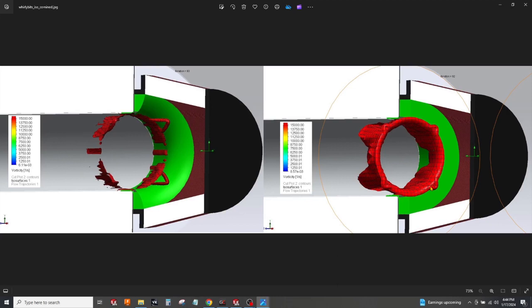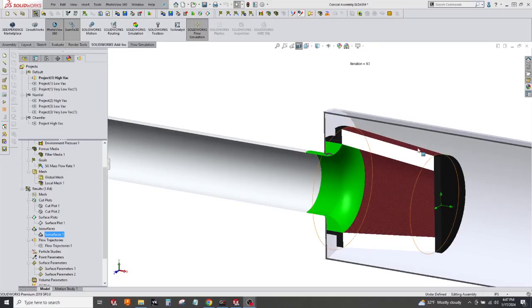So if you are constricted and you can only run a really small intake tube because of how it packages, this is where you're going to see the benefits of this type of thing. So I hope that is helpful. All right, so what have we learned? Well, essentially that velocity stacks are definitely a good thing, especially when you're running really high flow rates.